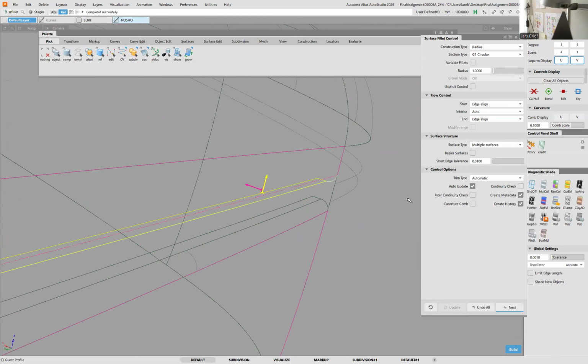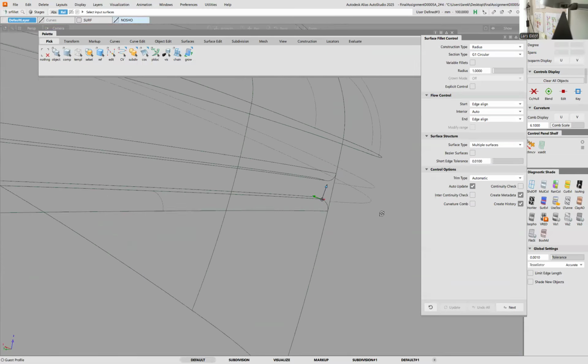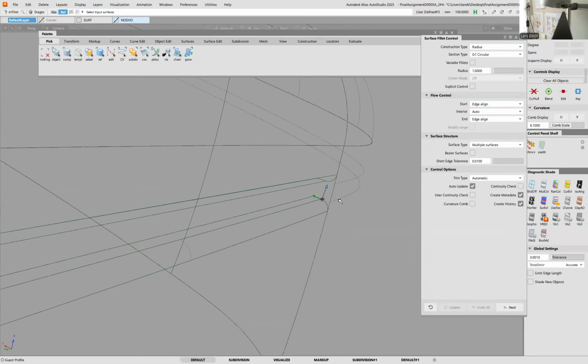So what we got here now is pretty much identical to what the panel gap tool did automatically for us. We have a gap, which is 2 millimeters. We have a flange, which was 2 millimeters before we rounded it off, but it should be around 1 millimeter deep.